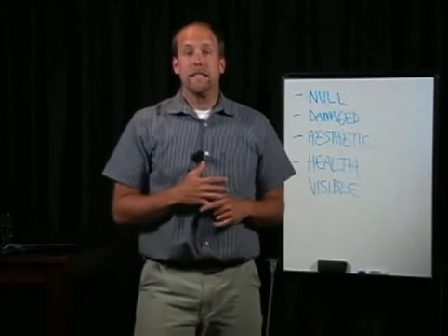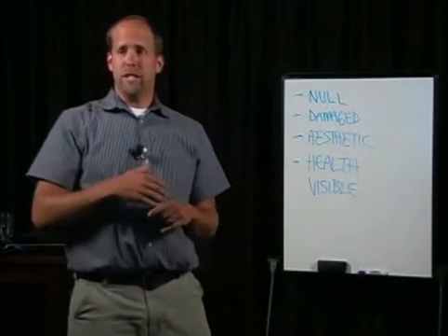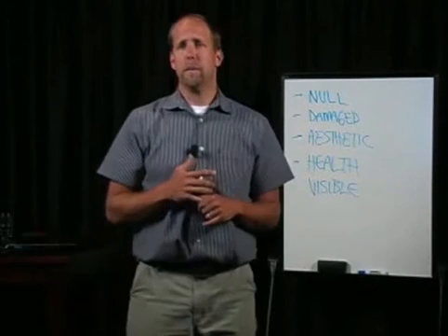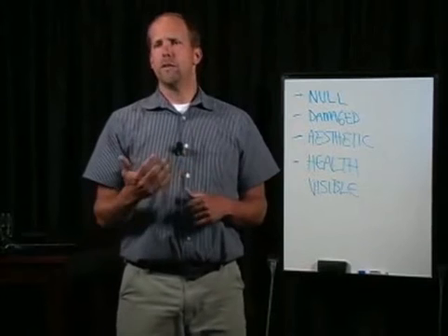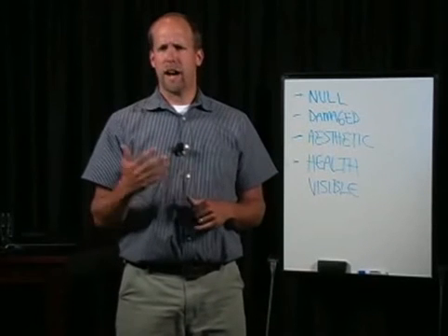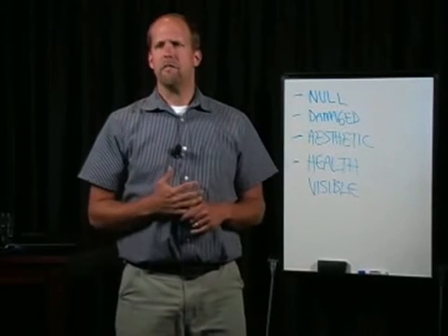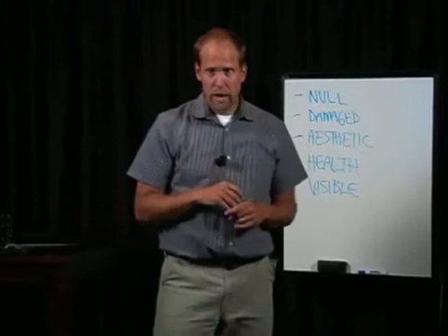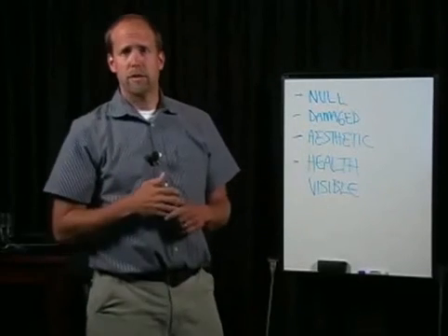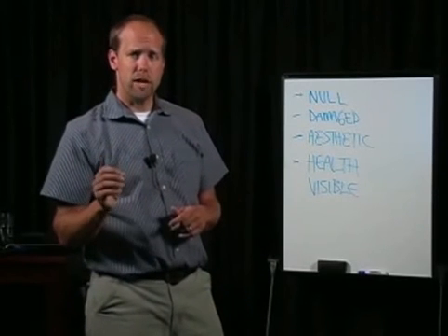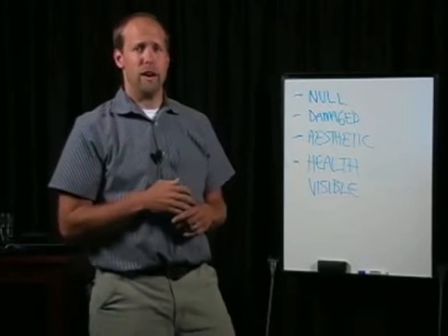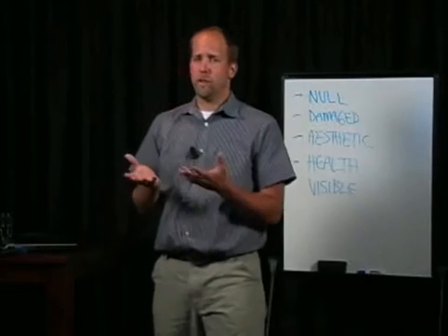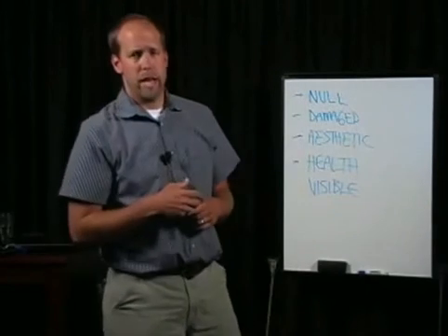Let's say that the inspector determines that further evaluation is needed in order to find the source of the moisture in the building that is supporting the apparent mold growth. The use of a moisture meter or other device can provide an objective indication of the amount of moisture in a building material. A closer examination of the area and the use of a moisture meter by the inspector results in discovering significant moisture coming from a dripping temperature and pressure relief valve of the hot water tank. The wall material is discovered to be wicking up moisture from the floor where the water drip is located.